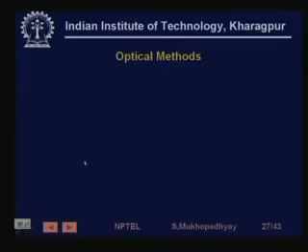These are all inductive methods. By the way, we might also mention that in many cases, suppose you have a basic sensor which senses position, and the signal is not very noisy, then you can differentiate the signal to get velocity.